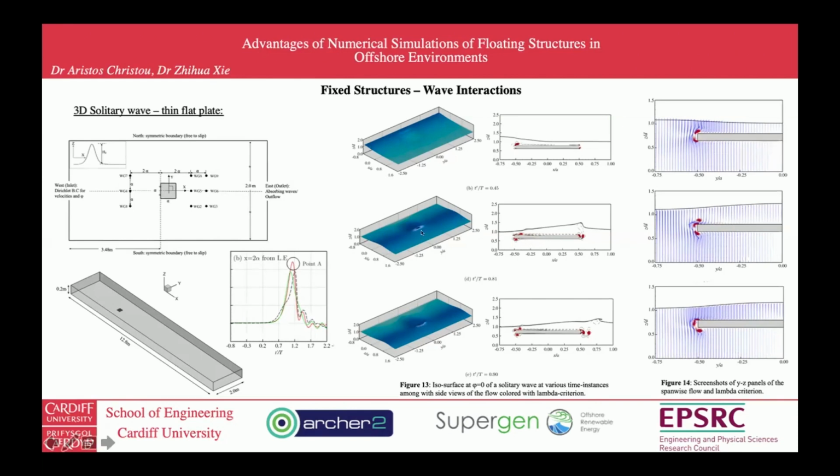And we noticed a big jump on the water surface over the plate, which was due to the ability of the flow to come from the lower side to the upper side of the plate through the lateral edges, the side walls, let's say, of the plate, generating some nice eddies here, interacting with the structure and the water surface.